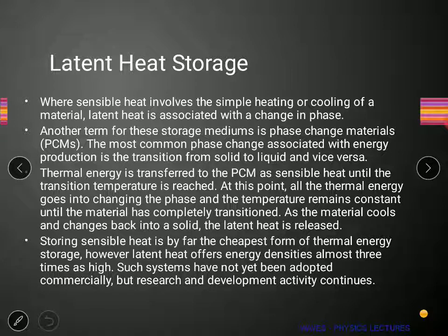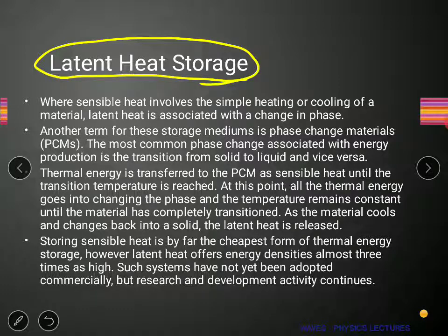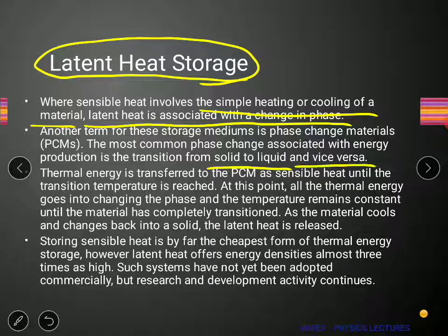Next is something called latent heat storage. Now this latent heat storage has some advantages over sensible heat storage, but this is still not practically used. This is still in the research phase. Sensible heat involves the simple heating or cooling of a material, but in latent heat there is a change in phase of the material. So if you heat a system so much that it transfers from solid to liquid or vice versa, that is nothing but latent heat storage.